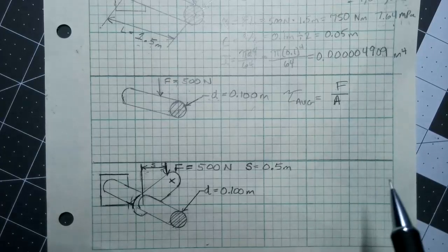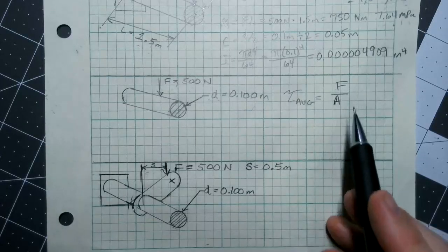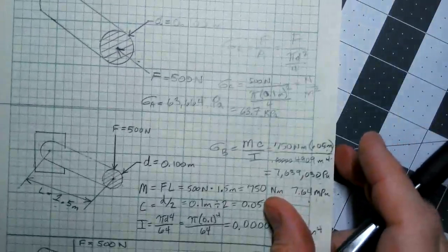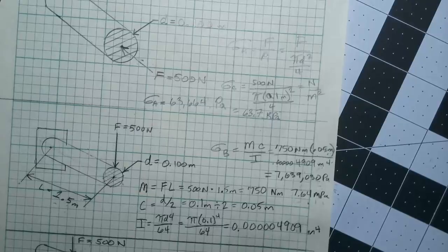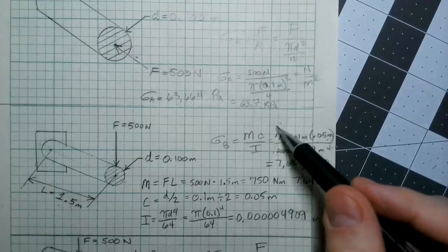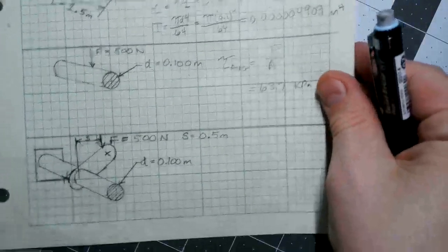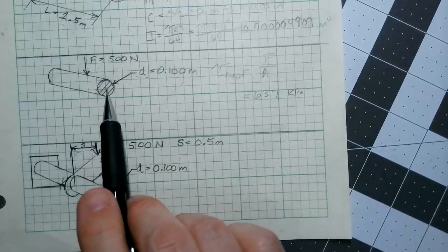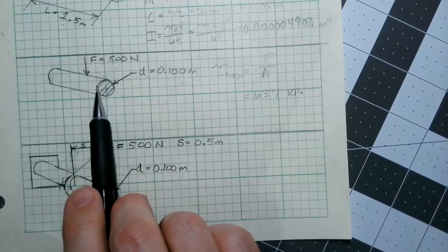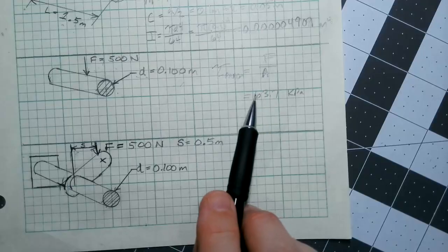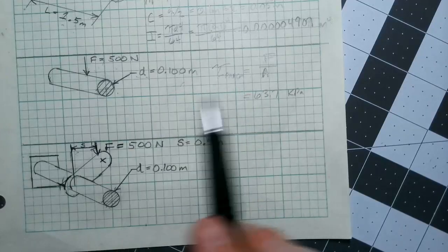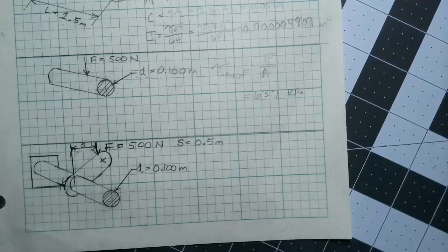Okay, hopefully you've come up with a solution. And if you look at this, it's really the same equation as we had before. It's F over A. So we know it would be the same answer as we had up above. It would be 63.7 kilopascals. Now, even though you get the same answer, that's not the same type of stress. This is a shear stress as opposed to an axial stress. And a shear stress will have a different failure mode than an axial stress, and it'll have a different rate at which it fails, a different strength that will be the limit for the design. So even though they have the same numerical value, they are two different stresses.